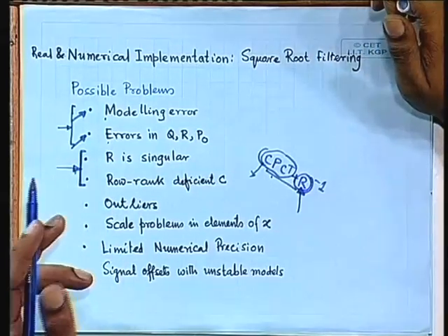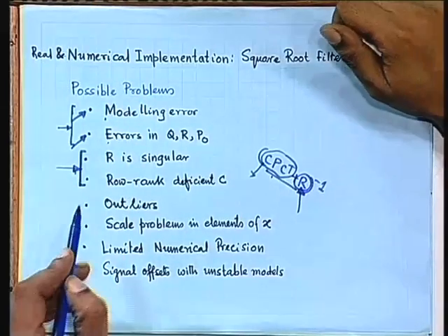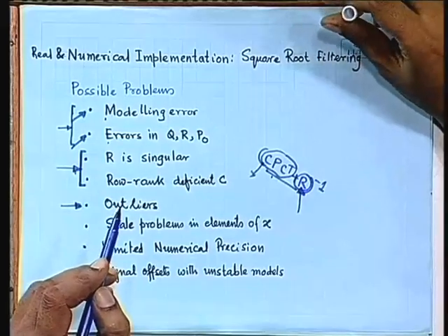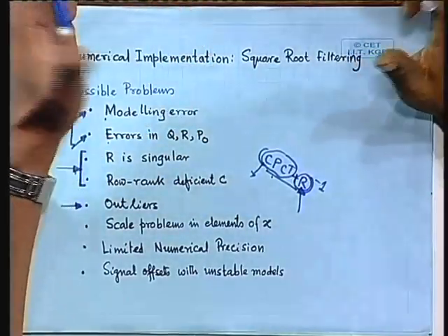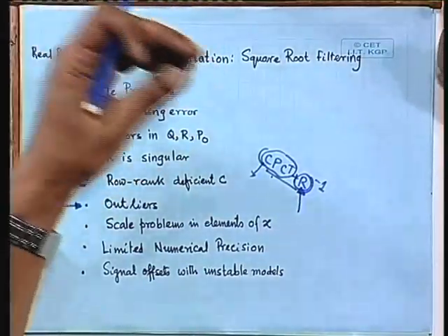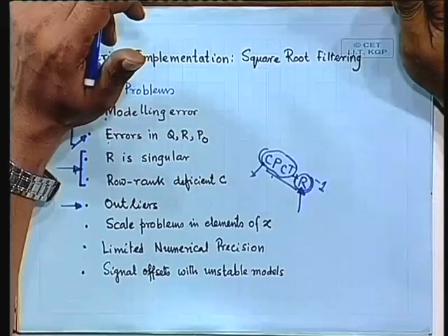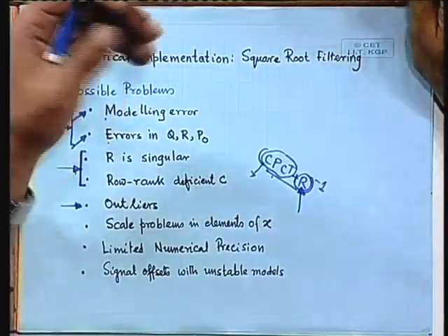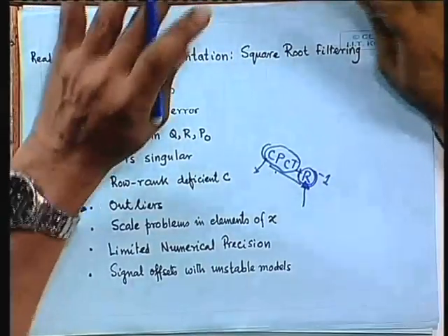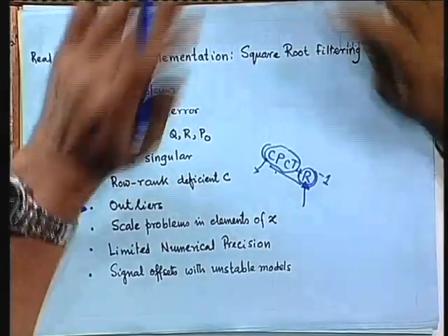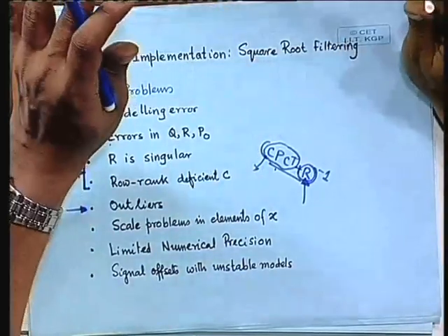There are several solutions, that is, check, sometimes add a constant non-singular matrix. Sometimes you may get outliers. Outliers means that you have generally observed that xi and eta are random, with certain kinds of Q and R, but sometimes, for some reason, you get some isolated data points which give you a peaky disturbance, glint kind of things. If you are not aware of those, you should first see whether you are having such samples. If you have such samples, it is better not to update based on them, because they do not really belong to the probability distribution which you have assumed for the filter. They are very sporadic signals which actually belong to a totally different probability distribution.